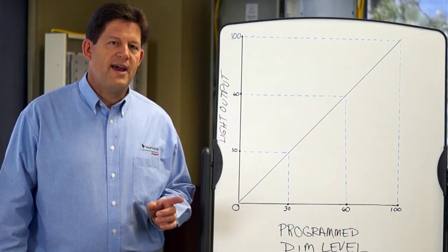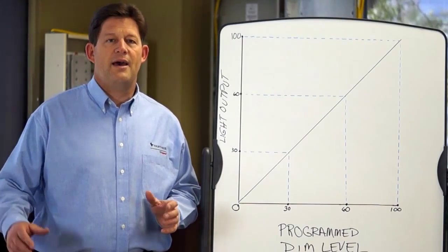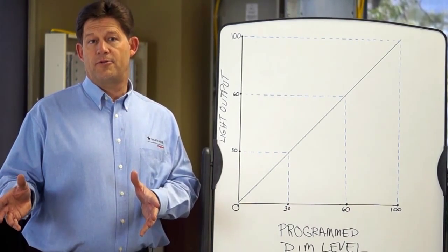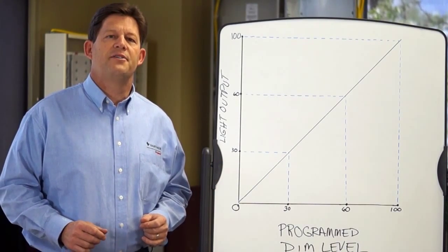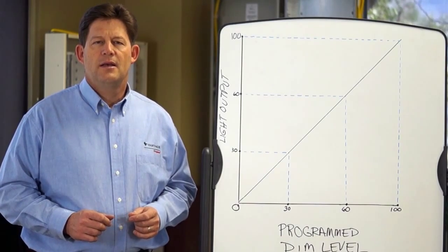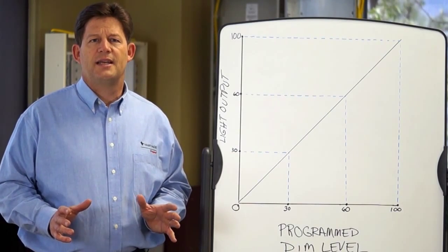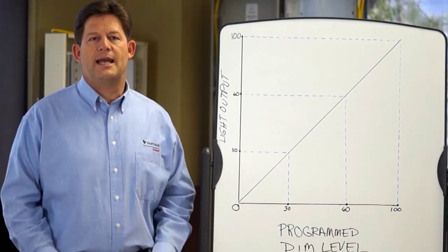But a key purpose of the Vantage system is to avoid the need to constantly change individual dimmers. If we have 8 lighting zones in a room, for example, and we have 4 distinct lighting scenes we want to achieve to provide different looks and set appropriate lighting for different activities, we certainly don't want to be adjusting separately the 8 different dimmers every time we want one of those lighting scenes.